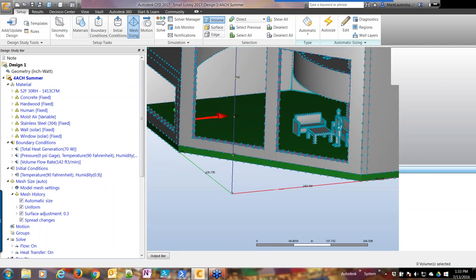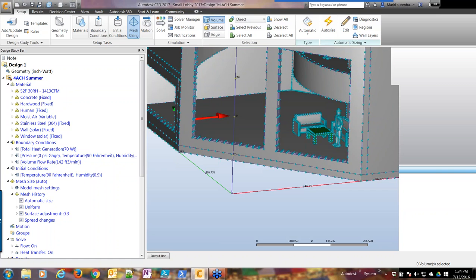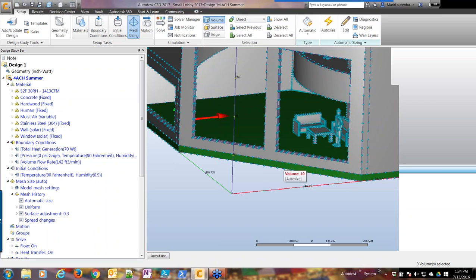You'll notice these dots. It has different amounts of dots in different areas because the software looks at two main things to determine how to do it: edge length and curvature. As the lengths of the edges get smaller or our curves get tighter, it knows that on smaller places it needs to break things up more. So the different edges of the different parts have a tighter amount of dots, and the dots are just representative of where and how it is going to break it apart.